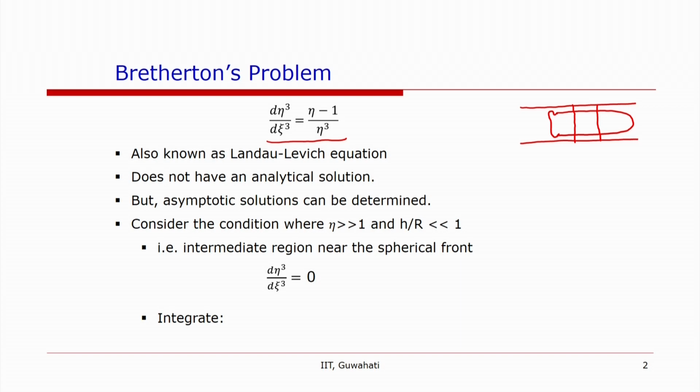The other application of this equation is when there is no tail of the bubble. For example, air is passing through a capillary which is initially filled with liquid, for example in coating applications. There also the same analysis can be used to find the thickness of the coating.